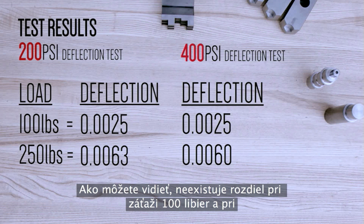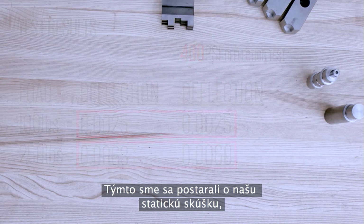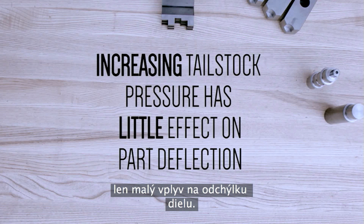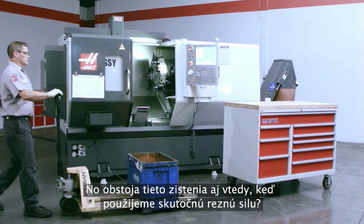As you can see, there's no difference for the 100 pound load and just a slight difference at 250 pounds. Okay, that takes care of our static test, and the results are clear. Tailstock pressure had little effect on part deflection. But do these findings hold up once we've applied real-life cutting force?